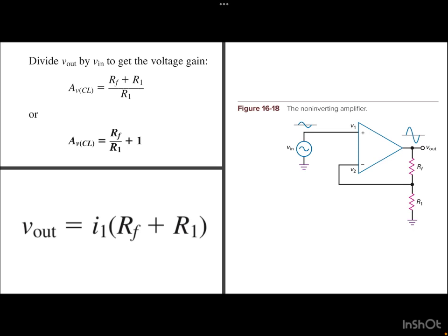The non-inverting amplifier is another basic op amp circuit. It uses negative feedback to stabilize the overall voltage gain. With this type of amplifier, the negative feedback also increases the input impedance and decreases the output impedance. An input voltage Vin drives the non-inverting input. This input voltage is amplified to produce the in-phase output voltage. Part of the output voltage is fed back to the input through a voltage divider. The voltage across R1 is the feedback voltage applied to the inverting input.